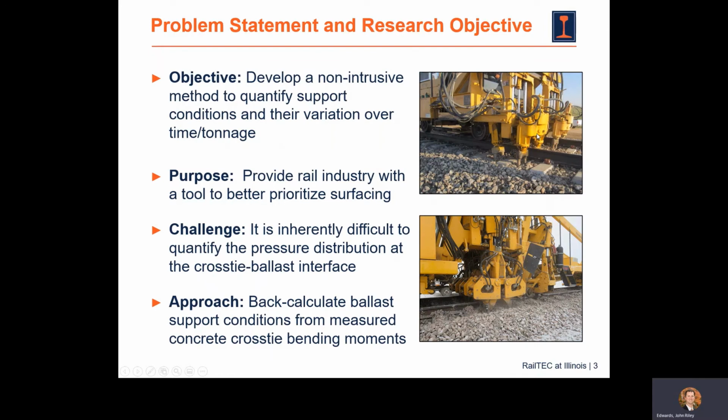So the objective of this project was initially to develop a non-intrusive method to quantify support conditions and how they varied over time. We were approached by several different entities that had an interest in prioritizing their surfacing or improving the design of their concrete crossties, and an instrumented crosstie that allowed us to understand what the pressure is beneath it allowed us to address both of those challenges.